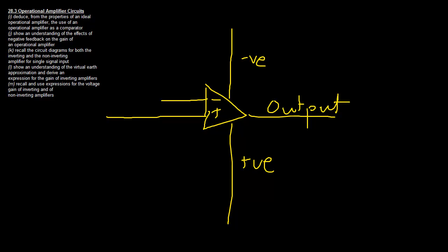Okay. Basically, if we recall, the formula we're going to use here, well, I don't like to talk about formulas too much in physics because I think it detracts from the core concepts, but basically, the output voltage is equal to, as I explained before, what this does is take these two inputs, the non-inverting and the inverting, and mash them together, except it multiplies the inverting one by -1.